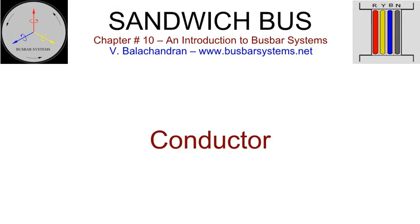Conductor. The conductor in a busway is either copper or aluminium. The conductors are always flat, with large width to thickness ratio exceeding 10. The geometry of the conductor will have minimal skin effect. The proximity effect will tend to compensate for the skin effect. The material utilization is very efficient.